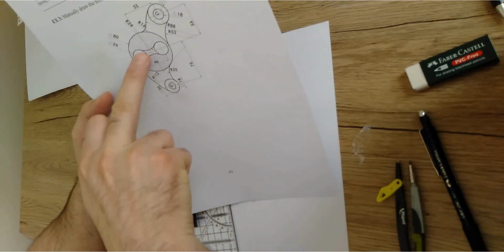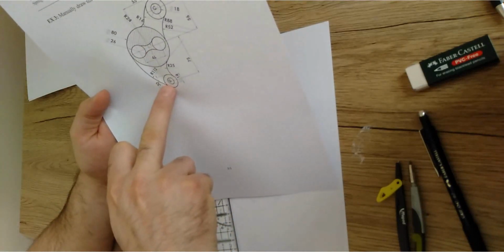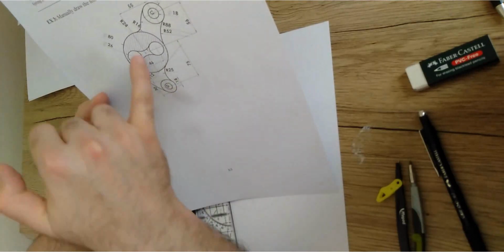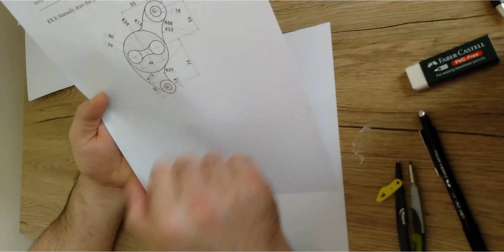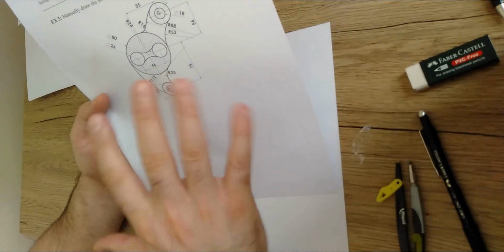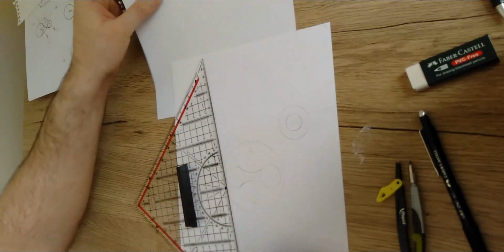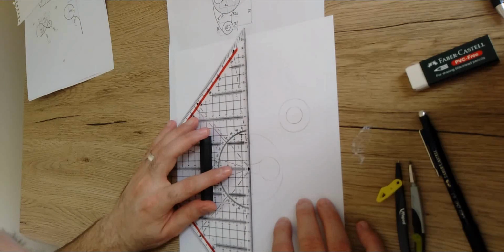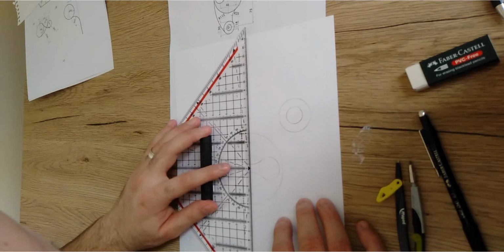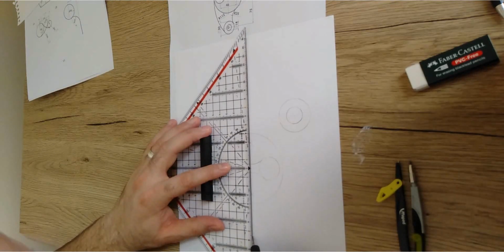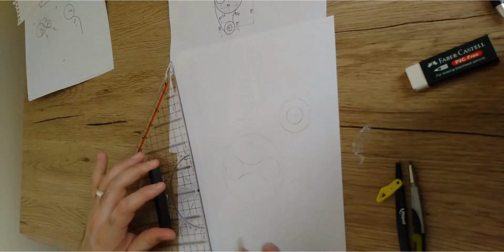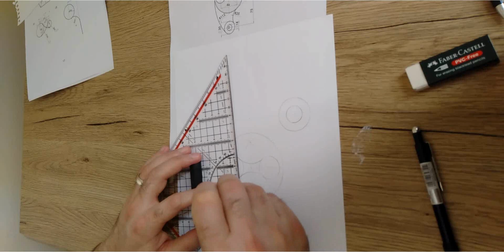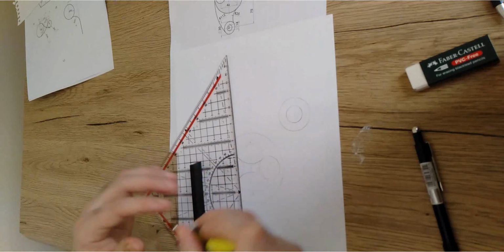So if you're standing here and I ask you to move down to the center point of these two circles, you're going to move down vertically over this vertical line by the 57, and this is what I'm going to do to locate the center point. Then simply you can draw the two circles. So from this center point, I'm just going to measure 75 millimeter. This should be the center of these two circles. Then the big circle has a radius of 15 because it has a diameter of 30. So the radius is going to be 15.